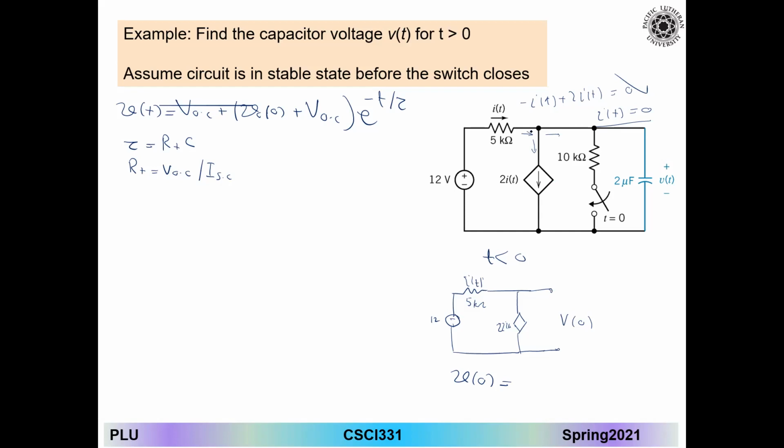So when you apply this, logically, if you find the current the way that you said, you have to assume I have here a voltage. I don't know what that voltage is. Then I can find the current here, VA minus 12 divided by 5. But I cannot assume this one could be just 12 divided by 5 to give me the current through this one. To find the current, you have to know the voltage across your resistance.